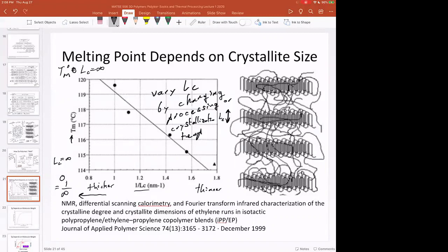It's how they do injection molding. This is going to be the crystallization temperature because we want this type of crystallite size to get these properties. But that's something to think about as we're putting polymers or thermoplastics through an additive process, what happens to the crystallite size, etc. And this will become important for material extrusion AM, and also for powder bed fusion, because we can start to control these temperatures.